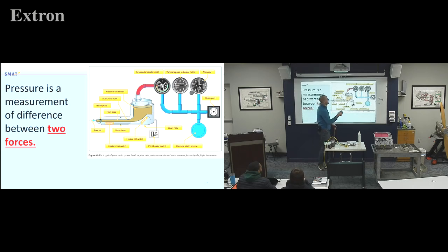no leak. Now what's going to happen if we do that is if I lower the pressure on this side of this diaphragm, but I leave the pressure on this side, that means that this side is going to be higher than that side, and my airspeed indicator is going to move, isn't it? It's not going to break the airspeed indicator as long as... now some aircraft are going to say don't add or take away pressure too fast, because they don't like the instruments going wow, wow. So that's a thing you want to check manuals on.